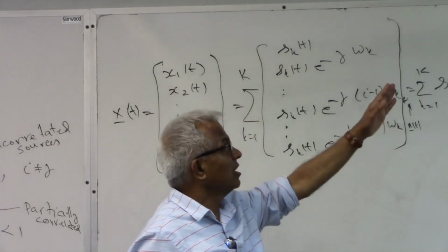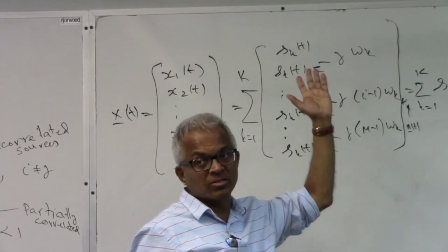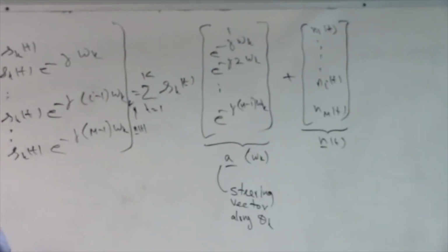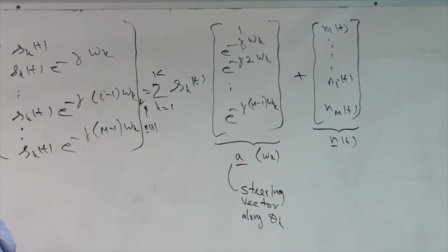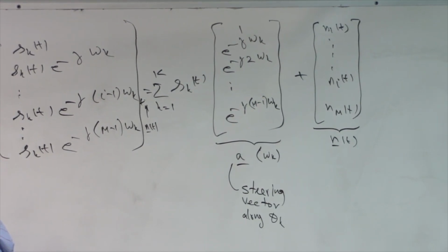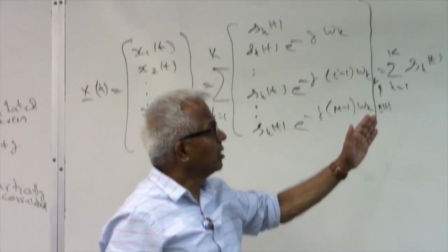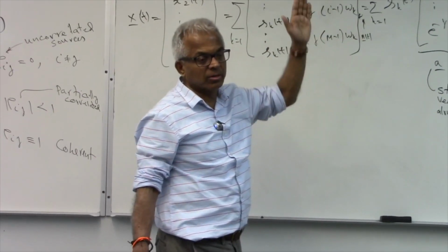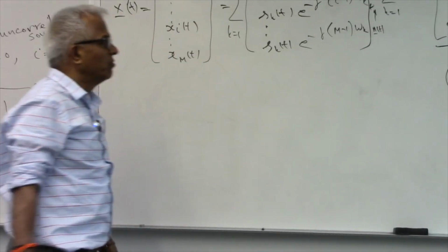So if things are uniform, then that's the same as a DFT vector, right? Along, and that's the reason I also brought in omega k. So if you take the DFT, then when omega hits omega k, everything is going to match up, and you should get a peak, and that's the beamformer.